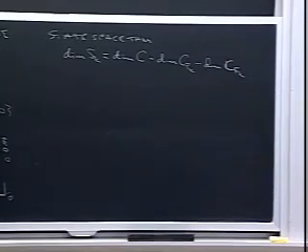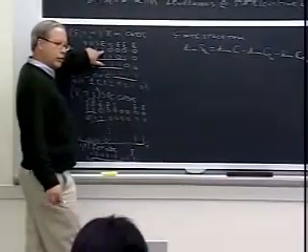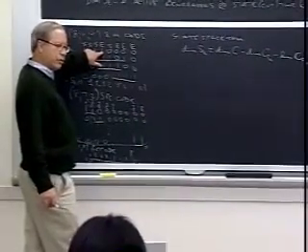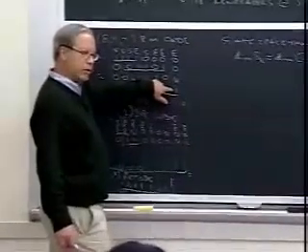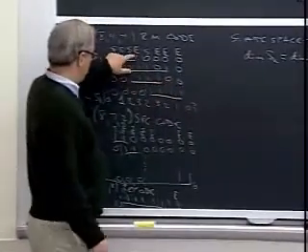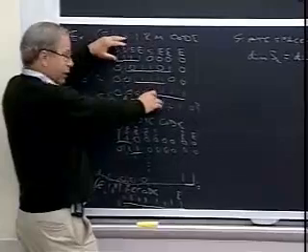All right, and we proved from the trellis-oriented generator matrix that the past subcode is generated by all the trellis-oriented generators that have support on the past, and the future by all the ones that have support on the future. So we take those out, and what do we have left?